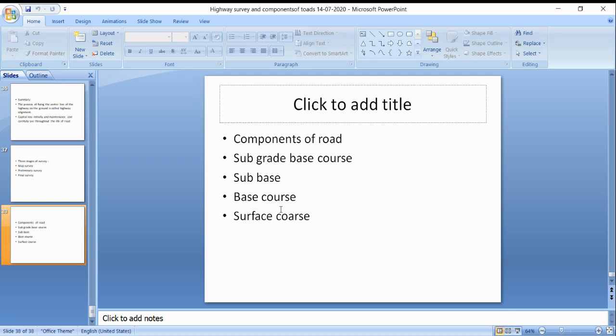In difficult terrains, if a maximum gradient has to be kept, the permissible limit gradient should be used, or if any exceptional gradients are there, we have to see that also. Minimum gradient should be provided for easy drainage works, because for easy drainage we have to provide a little gradient for the camber. It is preferable to allow the natural ground slope and take the road in embankment height of about 300 millimeters.